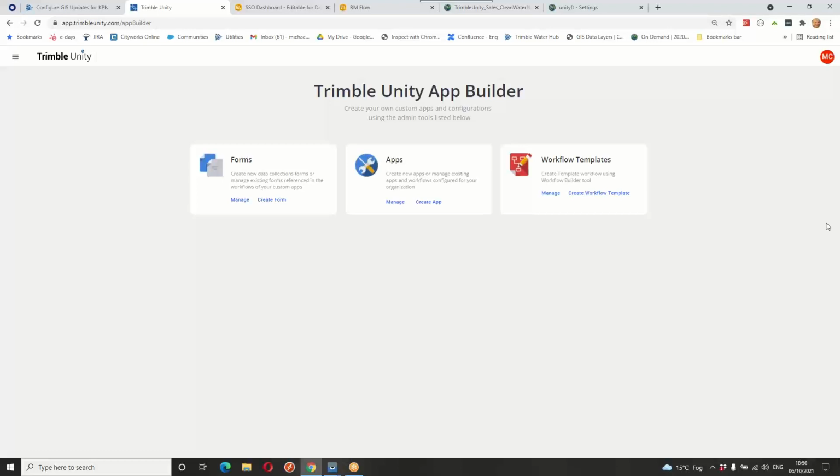If it's in a manhole, we can pick up flow level and velocity, rainfall, lots of different things like that. But what is really the power of Trimble Unity integrated with GIS, as Michael showed, is how you can deliver key performance indicators into your GIS. So not only do you see static GIS information, you're actually seeing real-time network data like pressure and flow and level, and have it update your GIS automatically. That was really the theme of the remote monitoring integrated with GIS.